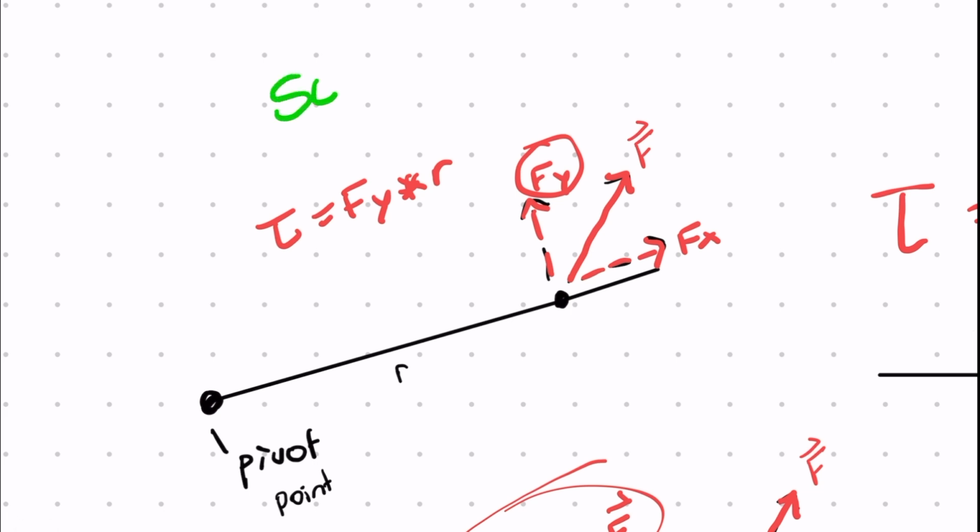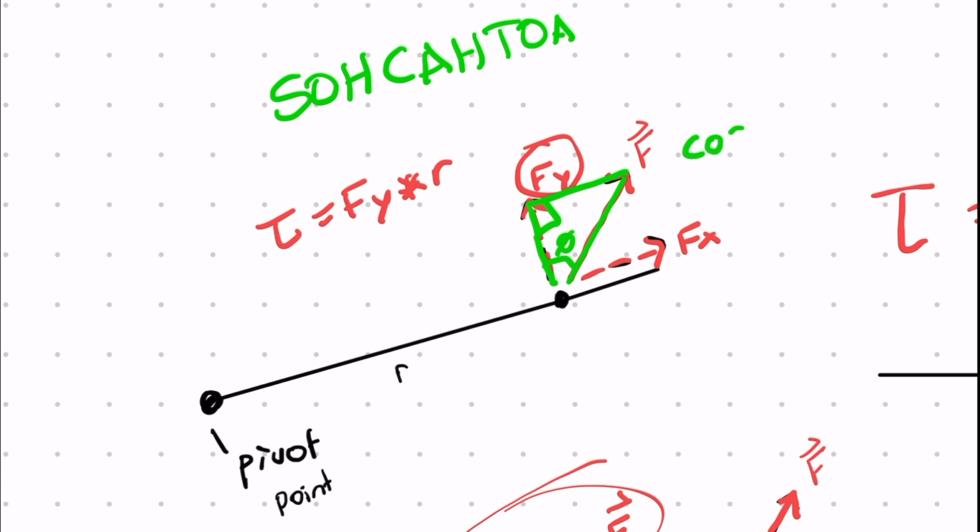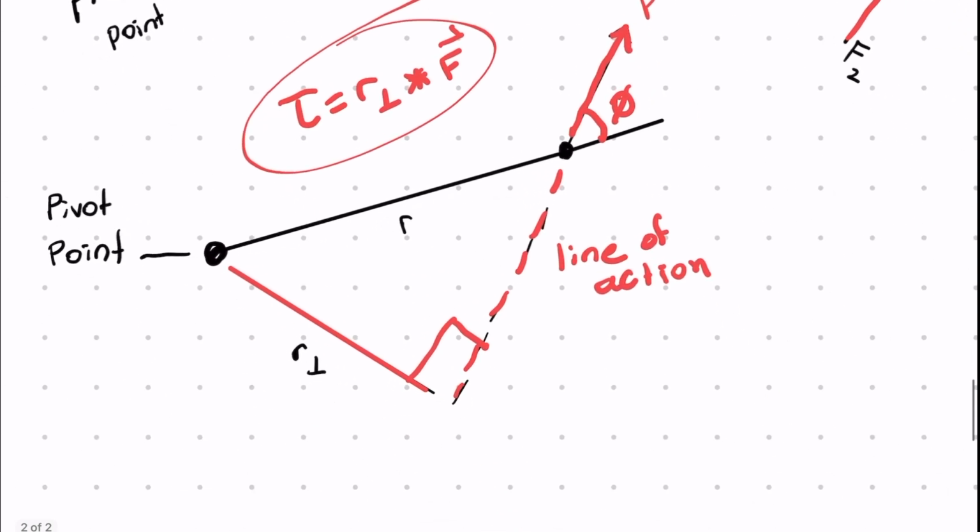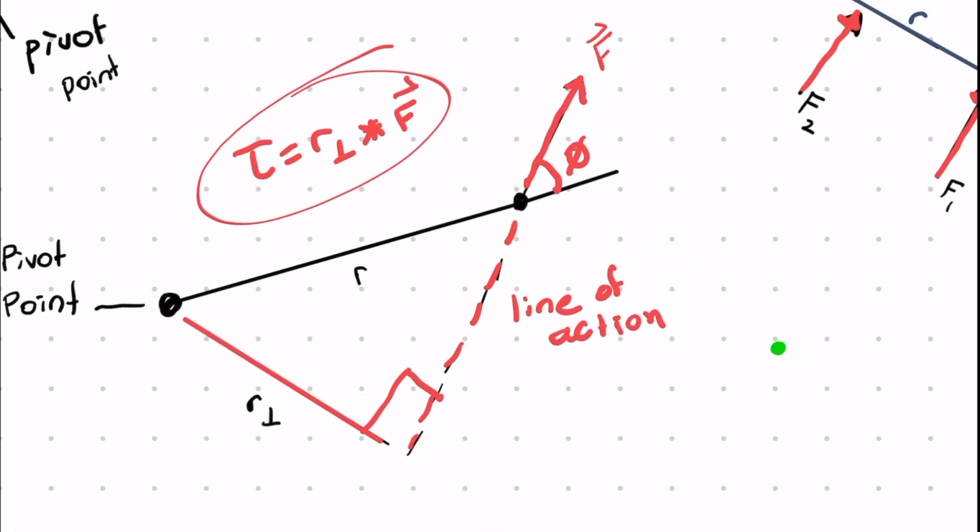Both of these methods are done with basic trigonometry and the SOHCAHTOA functions, where the magnitude of the force or the lever arm are the hypotenuse of a given triangle. Then, given the angle, either the moment arm or the correct component force can be found, depending on the situation and how it's modeled. For linear force, an object is at static equilibrium when the sum of its forces applied to it equals zero. We've calculated this in a previous lab by splitting each force into its components and adding each according to their dimensions.